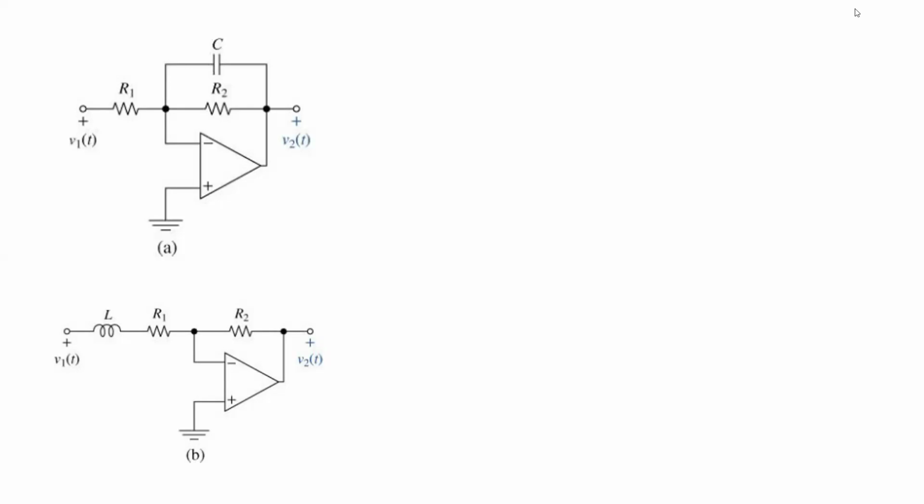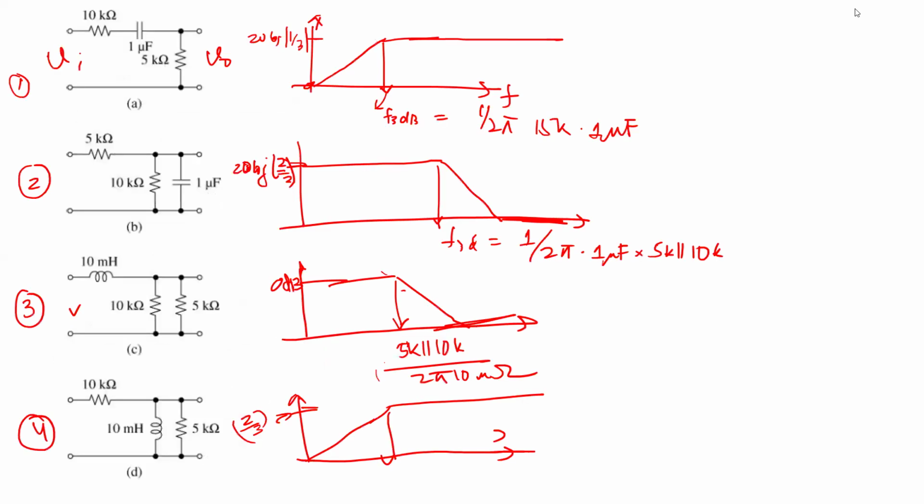With the inductor, you want me to repeat that part? Okay. So you're talking about the 3 and 4. Yeah. If you look at the input and output, see, the inductor and capacitor, because they're single order, right? One is omega L impedance, one is 1 over omega C. Which means that they will basically work the same way, except that it'll be the inverse of the frequency. So one is off at high frequency, the other one is on at high frequency.